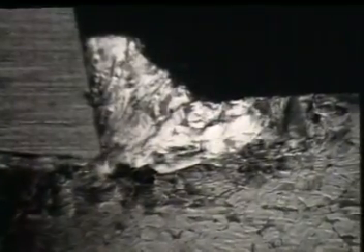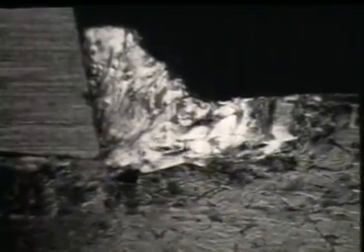There are two distinguishing features between cutting dry and with carbon tetrachloride. One is the incremental shear plane angle, the other the plastic deformation zone. When cutting dry and with a low speed, the plastic deformation zone extends a great distance in front of the tool. The incremental shear plane angle is approximately 25 degrees and varies inversely with the rake angle of the tool.